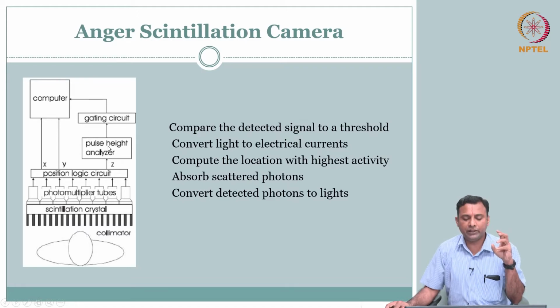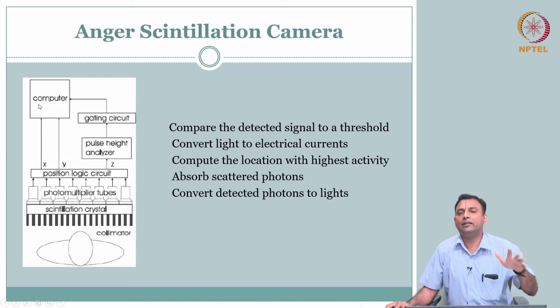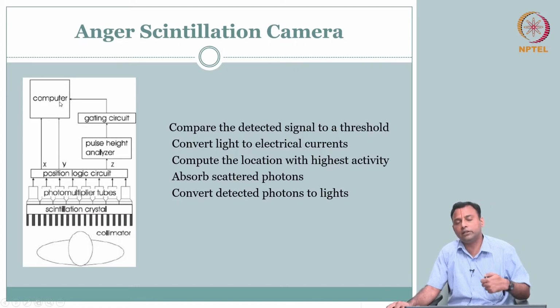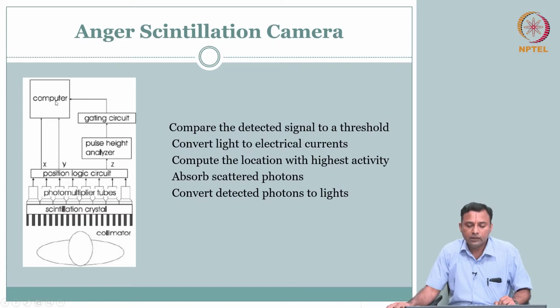And then you have additional circuits which can, as named here, pulse height analyzer, and then gating circuit, which energy you want to select, and then this is fed into computer, and then we will talk about what we can do, visualization or do this and reconstruct. So, the important aspect is here. You have to compare the detected signal to a threshold. So, here whatever comes, right, not all of them you may want to use it.